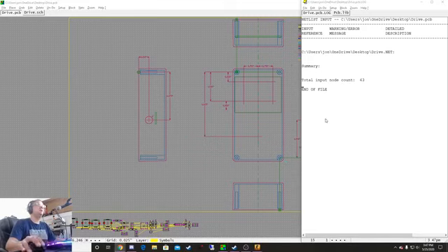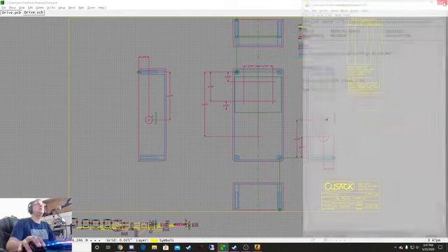So if there's errors, then we are going to try to fix what those errors might be, and again, we'll get into that stuff in a later lesson. But you could fix errors with, like, if it doesn't know what footprint it is, or if it can't find a specific pin because you called out an 8-pin part, but you told it there was a pin 10, things like that. But again, we'll deal with that later on.